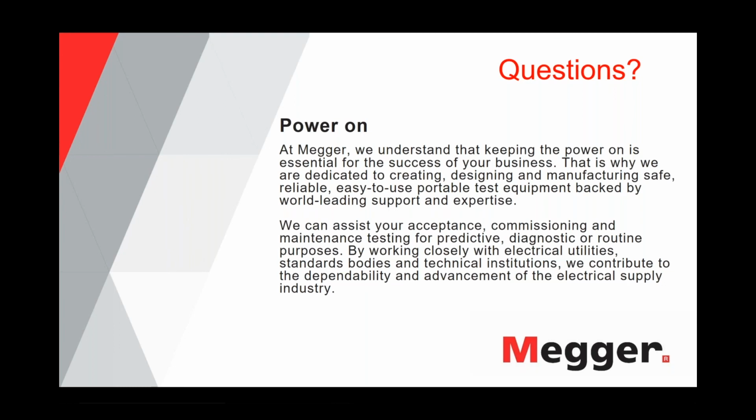order their assets by priority, or how much impact it would have to lose that cable. How important is it? How difficult is it to replace? That's another thing. And that is one of the determining factors on how often they would retest, and how fast they would have to act if something happens, or if they find a condition that they're not happy with. So the interval varies. So for the VLF test, for instance, there is statistic evidence brought to the table by two major international standards.